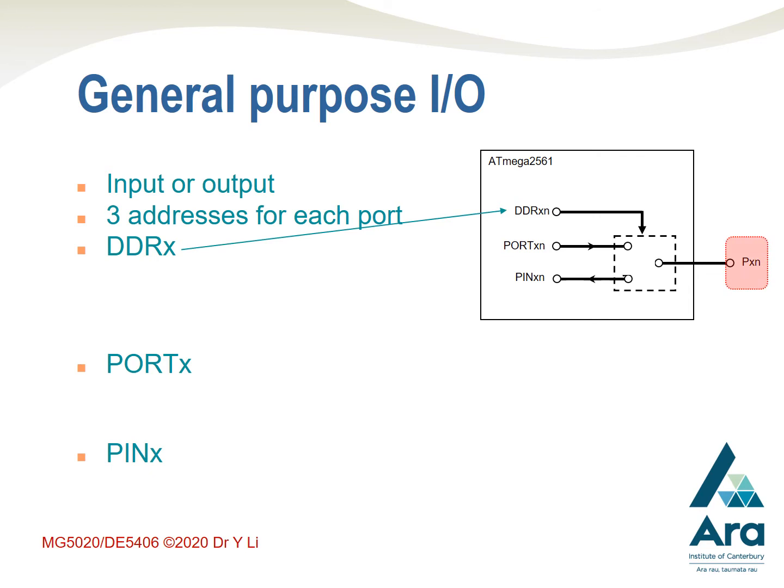DDRX is used to control whether the external pin is connected to PORTX or PINX. The other 2 labels are associated with the other 2 terminals in this diagram.